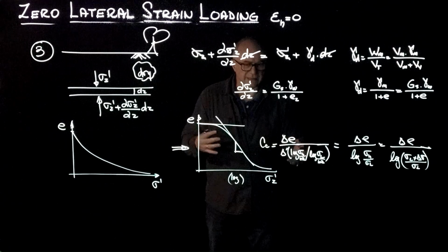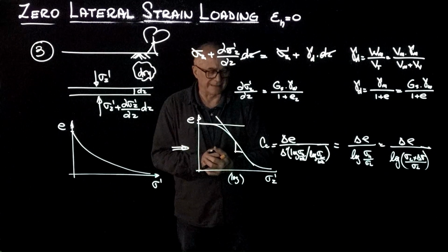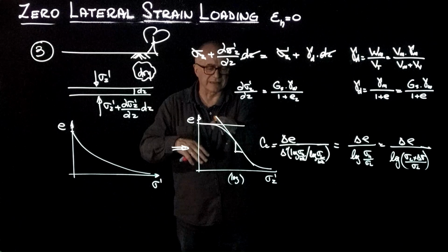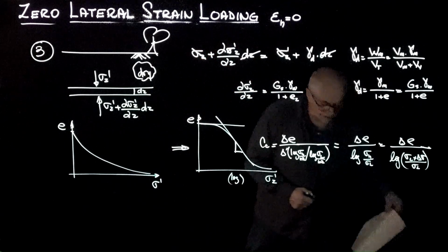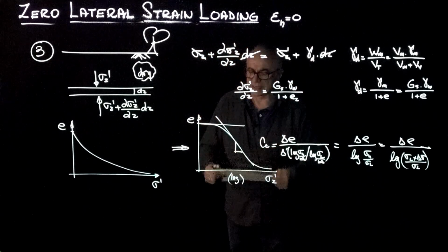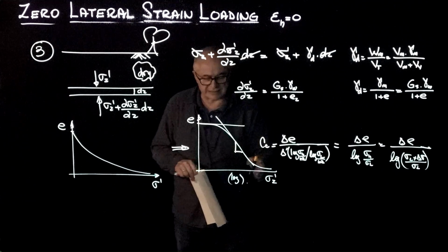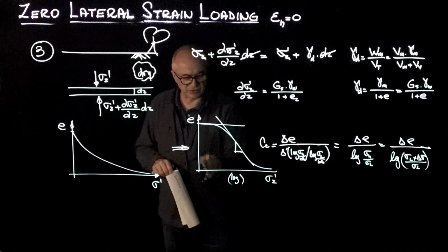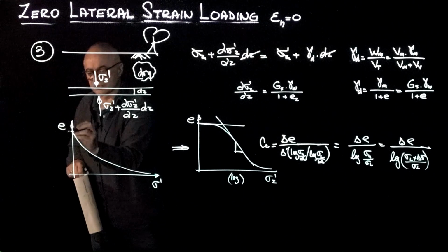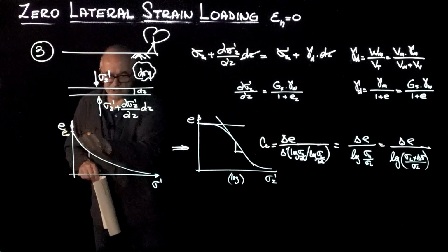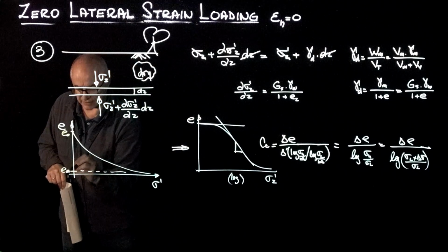This has been the tradition in our field, and I think that we have to begin using continuous functions, which are versatile, do not give us the inconvenience of figuring out what σ_p' is, and curve fitting errors, and there is no derivative at the intersection point, which creates numerical instabilities. So let me write a couple of asymptotically correct equations. And that is very important when we want to have something robust. It has to be asymptotically correct in the sense that as the stress goes to 0, we don't see that in logarithmic scale, we certainly see it here. As the stress goes to 0, the void ratio goes to an asymptotic value we are going to call e_0. And as the stress goes to infinity, the void ratio is going to go to another asymptotic value, e_infinity.